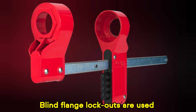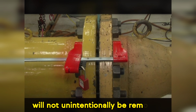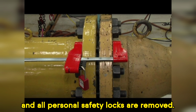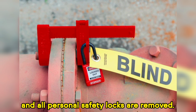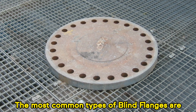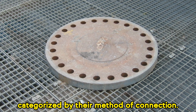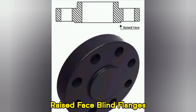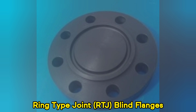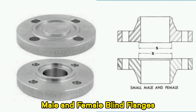Blind flange lockouts are used during maintenance on piping. It ensures the blind will not unintentionally be removed until all work is complete and all personal safety locks are removed. The most common types of blind flanges are as follows, categorized by their method of connection. Raised face blind flanges, flat face blind flanges, ring type joint or RTJ blind flanges, male and female blind flanges.